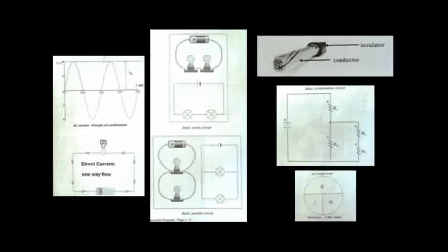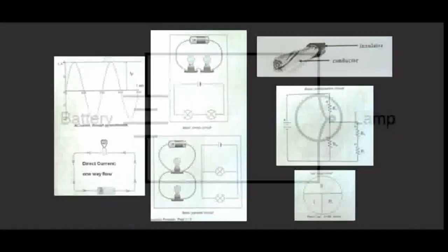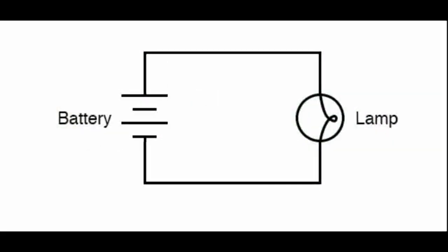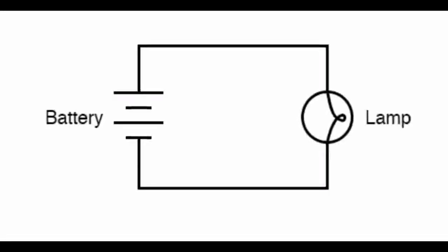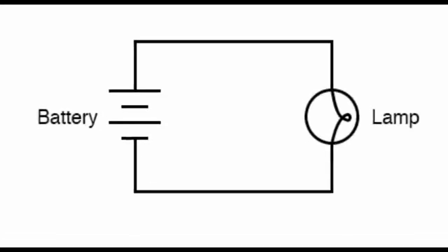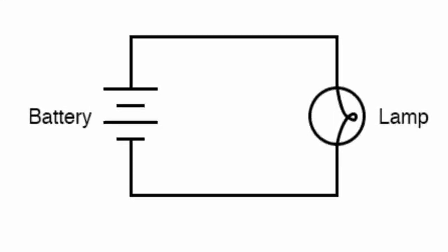The three main parts are voltage, a load, and a conductor. The voltage, in this case, will be supplied by a battery. The load will be a simple lamp or something we are trying to get to work. The conductor is the wire we use to hook the battery to the lamp or to transfer the current. When you take one side of the battery and wire it to the lamp, and wire the other side of the lamp back to the switch and the other side of the switch to the other side of the battery, the electrical energy will cause the lamp to produce light.